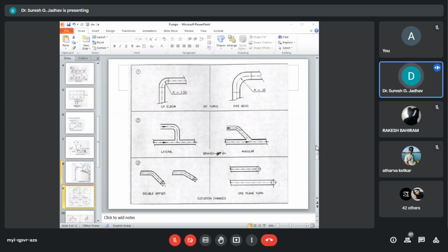Spool pieces shall be provided to facilitate pump removal because the maintenance requirement is relatively frequent. If the pumps are designed for multiple duty, the suction manifold and the discharge manifold shall be arranged nearer to the pumps to make it operator friendly.